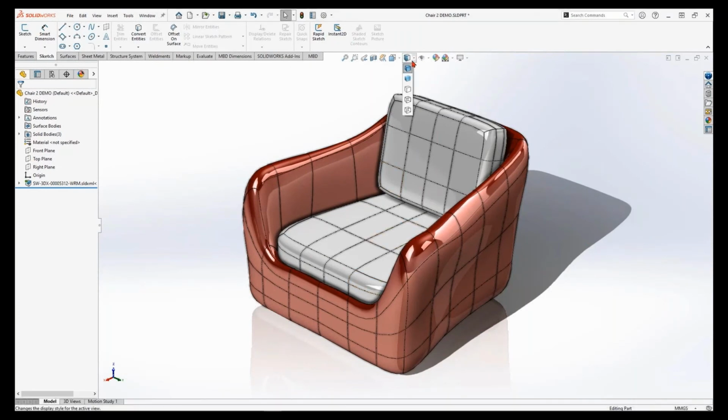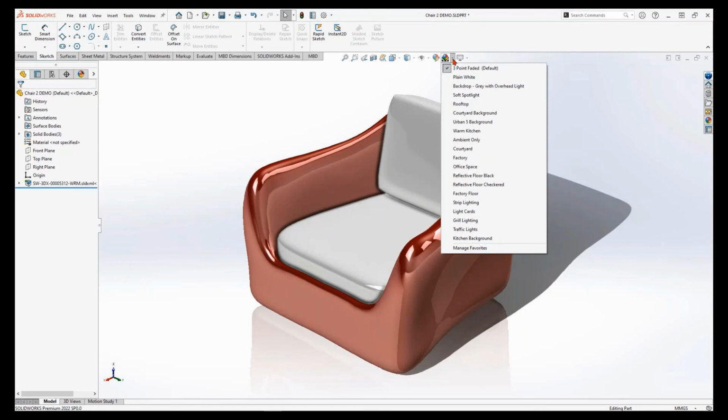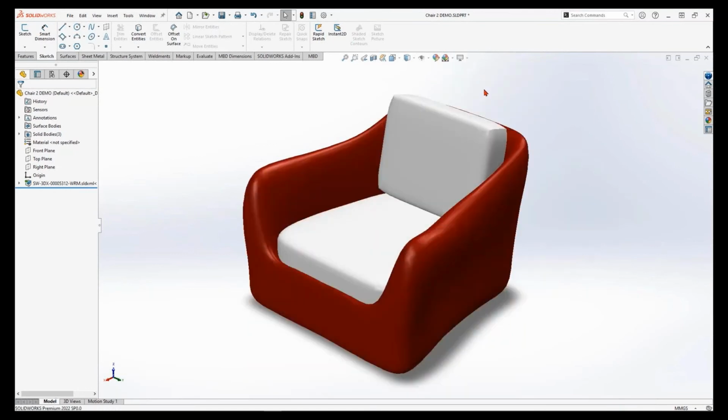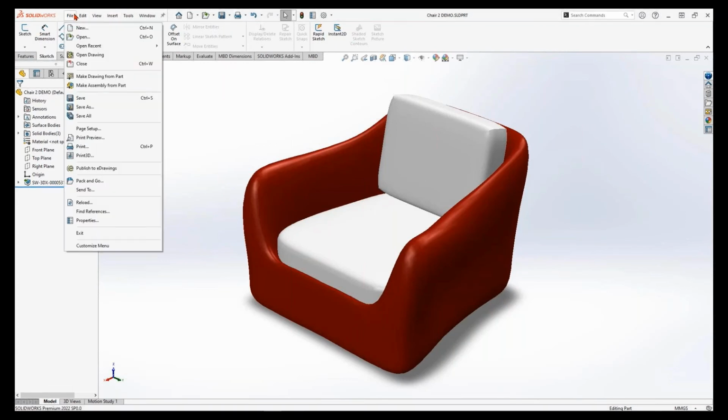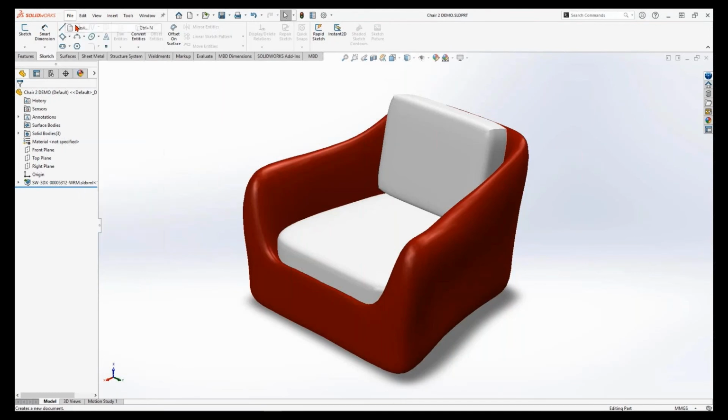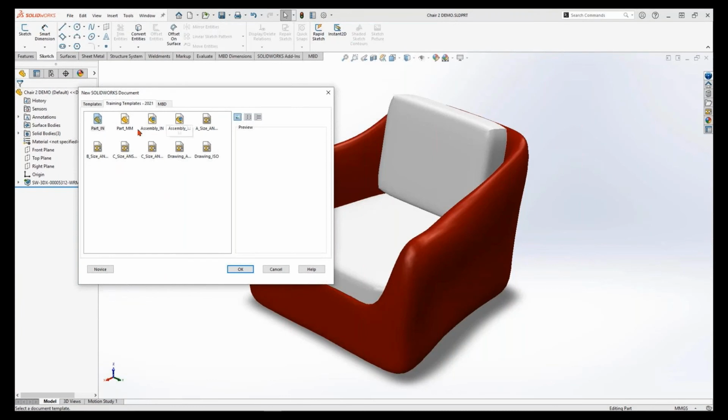Now remember, this was done in xShape and I just imported it into SOLIDWORKS. And guess what I used? 3D Interconnect. 3D Interconnect brings almost any file format into SOLIDWORKS. So it's connected. You see the little arrow on the left in the FeatureManager that shows it's connected to the original file. That's important because if I want to change my model, it has to be connected.